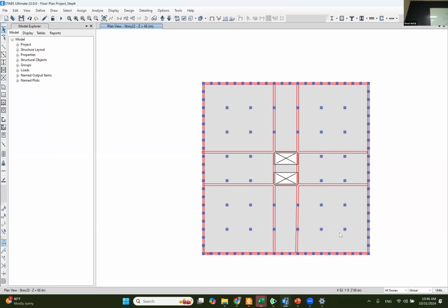If these 2 columns are on this wall, that's much better. But if it's not, that's okay. All right. So, and then run the model, get the shear lag, get the interstory drift, and I expect at the story that has the outrigger, the interstory drift is going to be almost 0. Like you'll find that the story drift is looking like this, and then goes back, and then goes all the way down. Okay, because that's a stiff wall, it doesn't deform much. So it's going to affect the displacement, it's going to affect the interstory drift, affect everything. And if you want to add a third outrigger, add the third outrigger and see how it's going to affect your model.